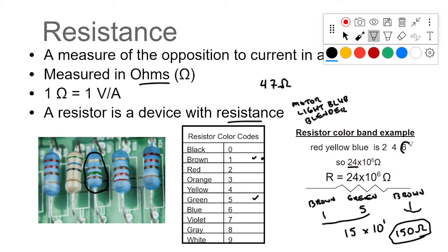You take that third number, and it's the exponent on the times 10 to the something, right? And you put it right there. You can see that you can get anywhere from 1 ohm up to millions and billions of ohms with this thing. So it's a pretty handy code with only 3 digits, to be able to express that many numbers is pretty remarkable.